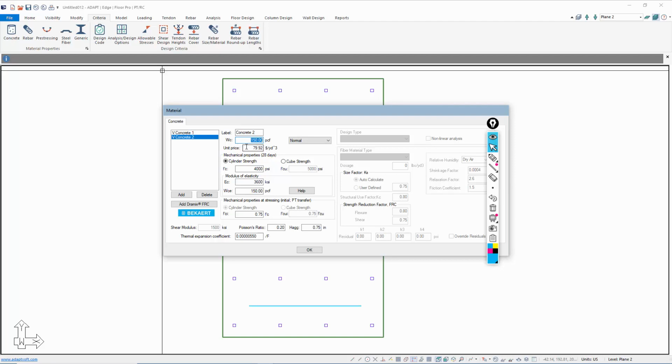If we're not really accounting for these walls in terms of a global model, we're just modeling them to get load transfer through them down to the podium level. So if we wanted to run the entire structure for simulation of a mixed concrete and other material global structure, that would be harder to do because then we have to simulate the stiffness of those components and the different conditions of the components in terms of their fixity to slabs and to the podium. So this is primarily only for load transfer down to the podium.